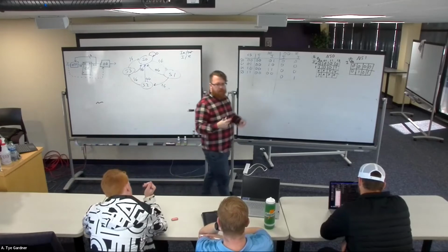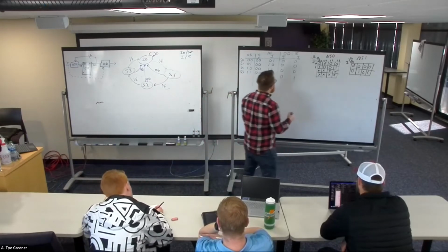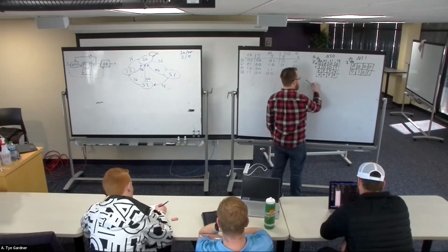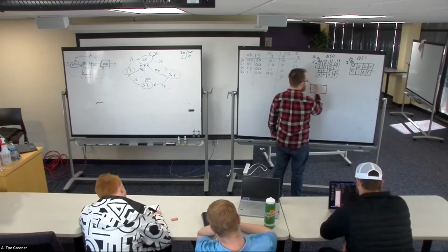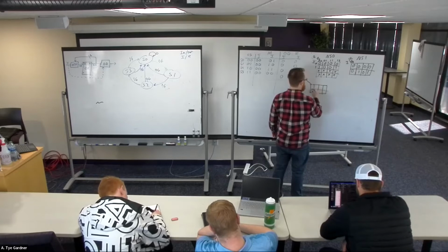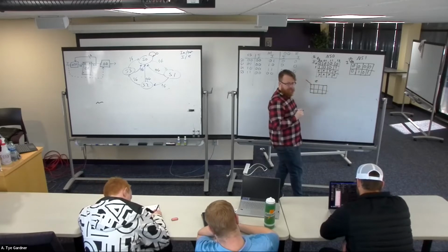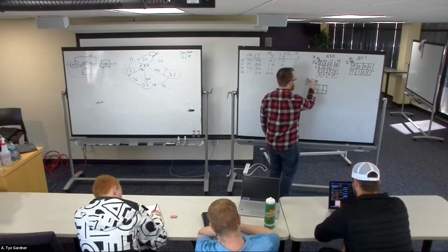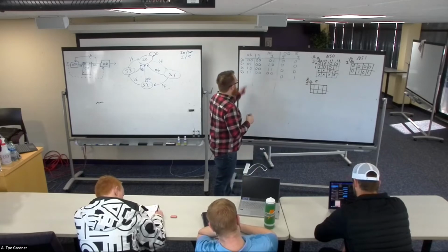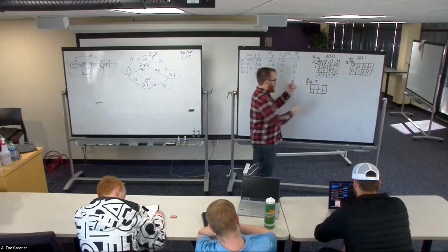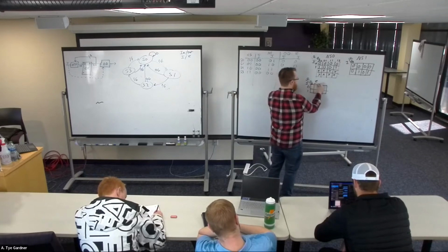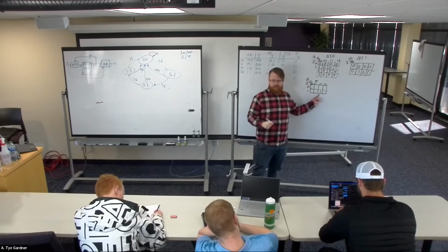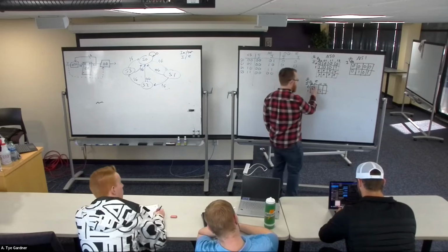Last one, the output decoder. The output decoder is easy because we have just a bunch of zeros, right? So we're going to do the same thing because this is a Mealy state machine. So this is the K-map for Z. Same situation, Q0, Q1. And then we just know if we're 1, 1, 1, which is easy to find, right? That's 1, 1, 1. Everything else is 0.